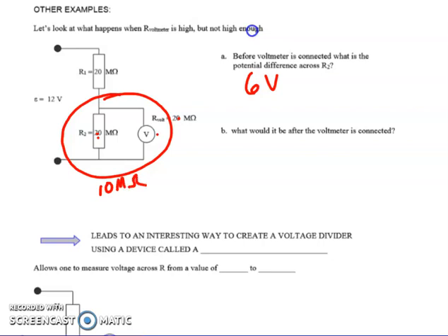Now you could use the 1 over R equation: 1 over R equals 1 over 20 plus 1 over 20, and solve like that. You'll still get 10 mega ohms. So this is in series with this whole thing. So we have 20 plus 10 is 30. Oh, I'm sorry, let me take that back. So that changes things. This whole branch has half the resistance of this resistor.